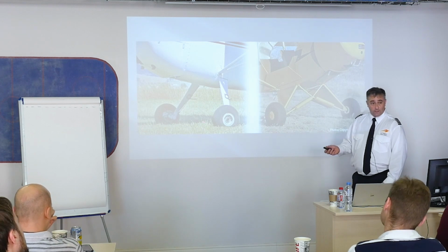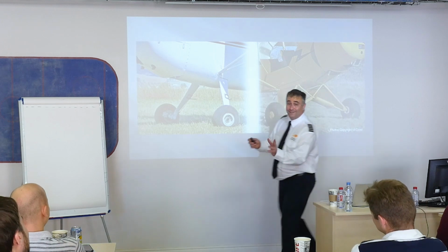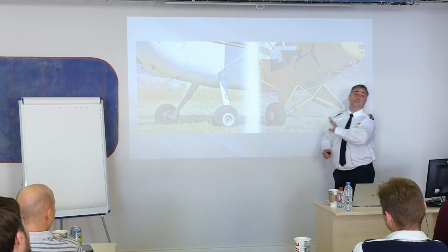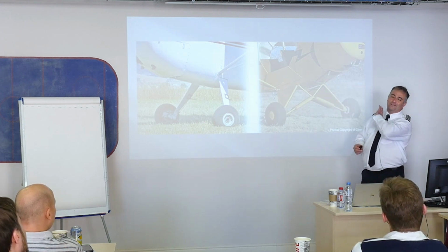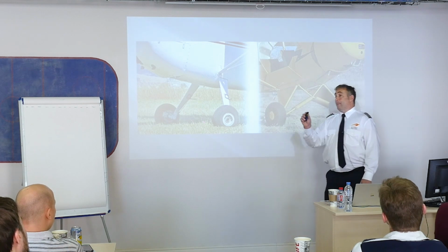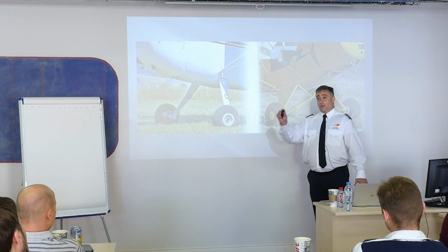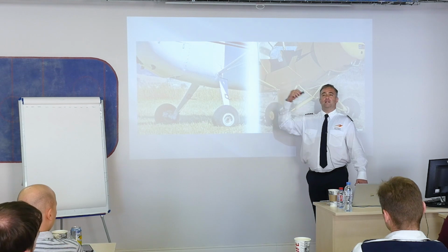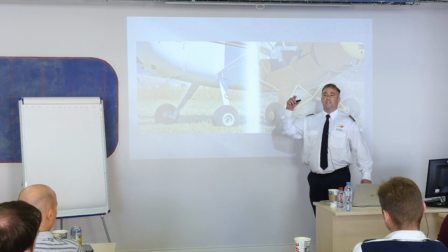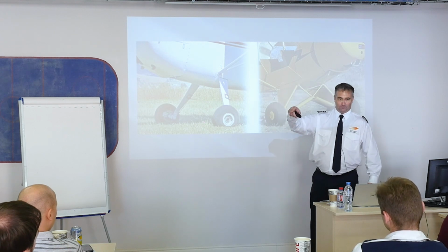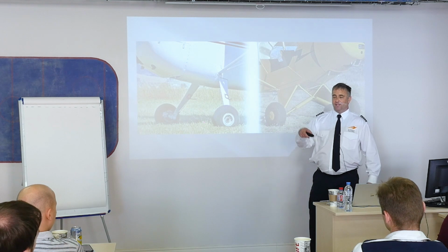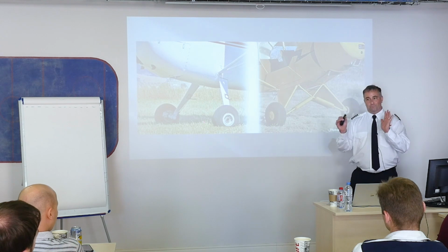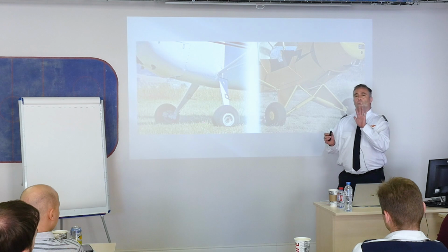Number one, I know that your instructor doesn't know how to do it because I've flown with him. Until you get 2,000, 3,000, 4,000 hours, you're not going to know how to do a crosswind. But try. Crosswind takeoff, crosswind landing, all of it. The pilot community is terrible at doing these things. But we're going to land on which gear first? The main gear. Start thinking right now that you're going to land on the upwind tire. That's where you land. If you guys would just land on the main gear, I'll be happy. Not the nose gear, in other words, but on the upwind tire.